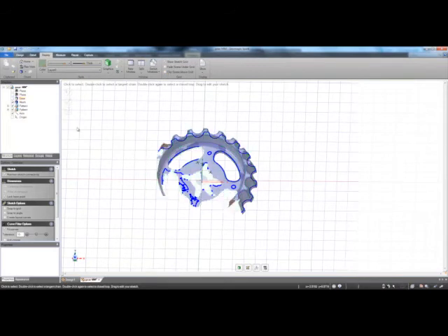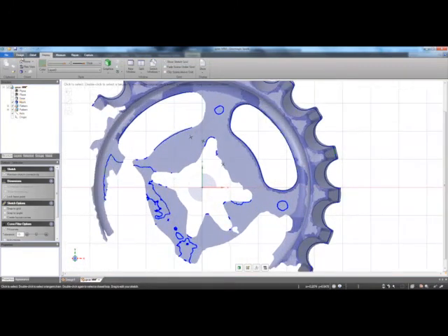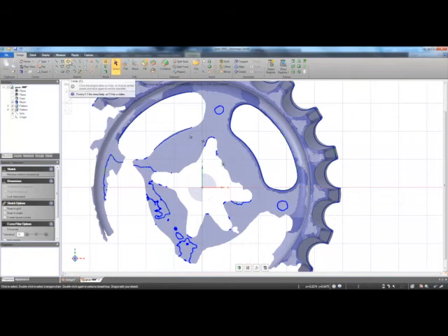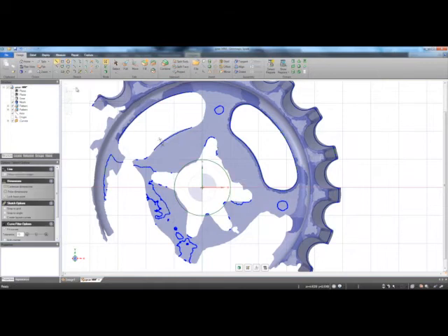I'm going to turn off this solid body as well. I'm going to square everything up. Go back to the design tab. I'm going to go ahead and choose circle, and I'm going to base it off of the center of my world axis and just build a circle out. And now there are many ways to create these little teeth right here. I'm just going to show one, which is just taking this line sketch tool, left mouse button, and you'll see that it actually snaps to the mesh as well, which is kind of nice.